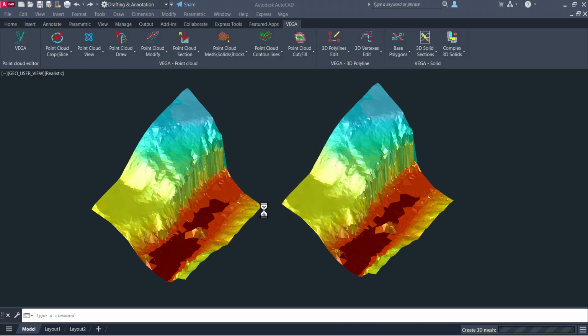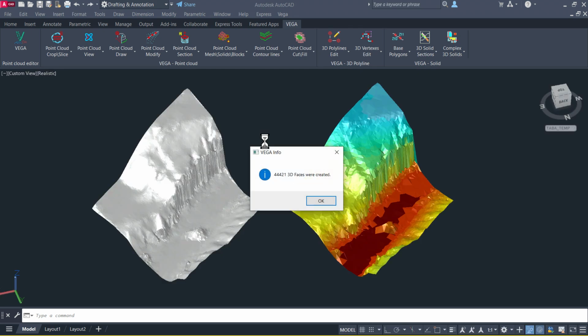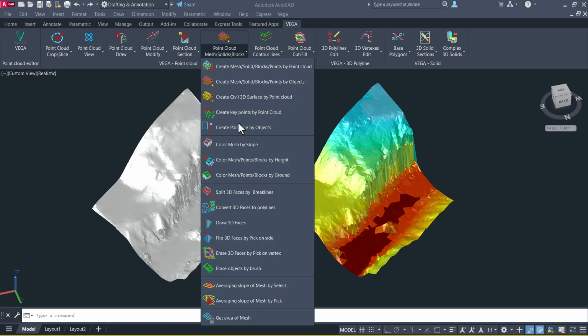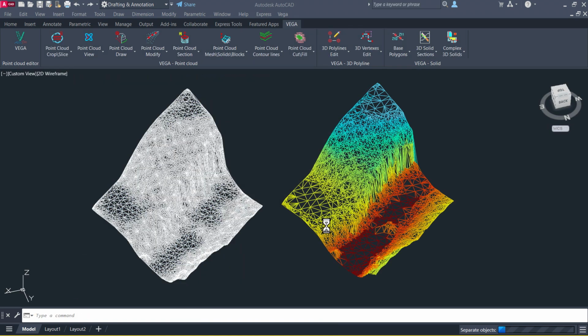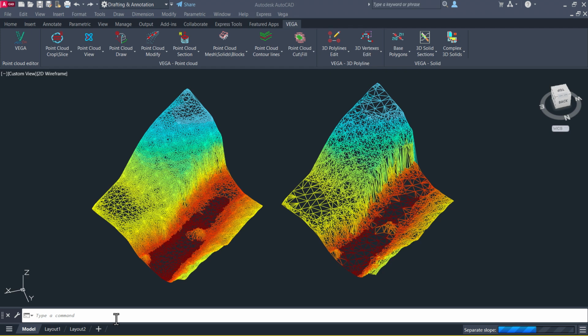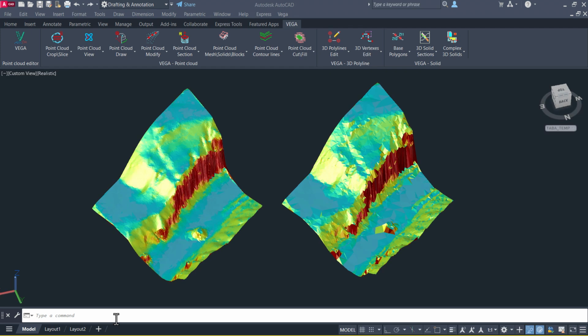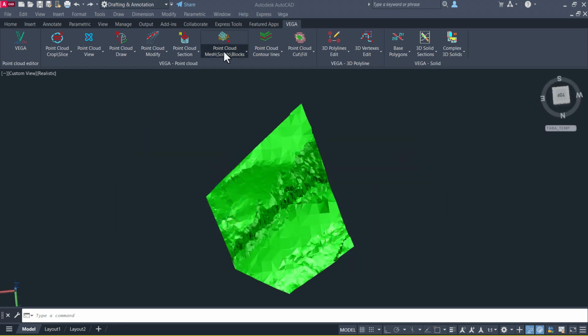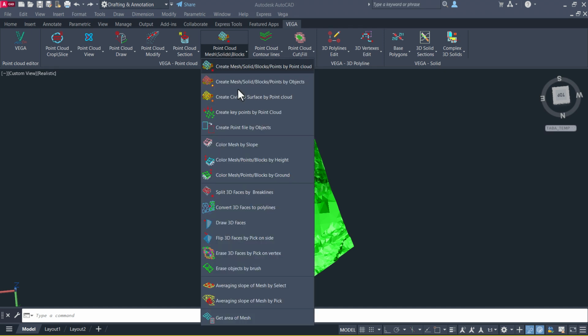Let's look at this surface from the 3D modeling when we want a smoother, nicer result. We're going to color it exactly the same as the unsmoothed one in height. You can see how much smoother and nicer the image has become. Let's see what it looks like if we color it based on angle. We can convert generated meshes into 3D solids, civil surfaces, or points text files.